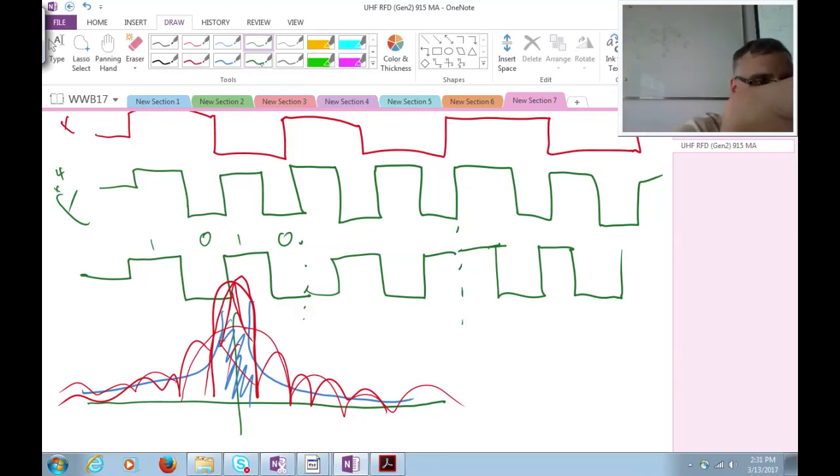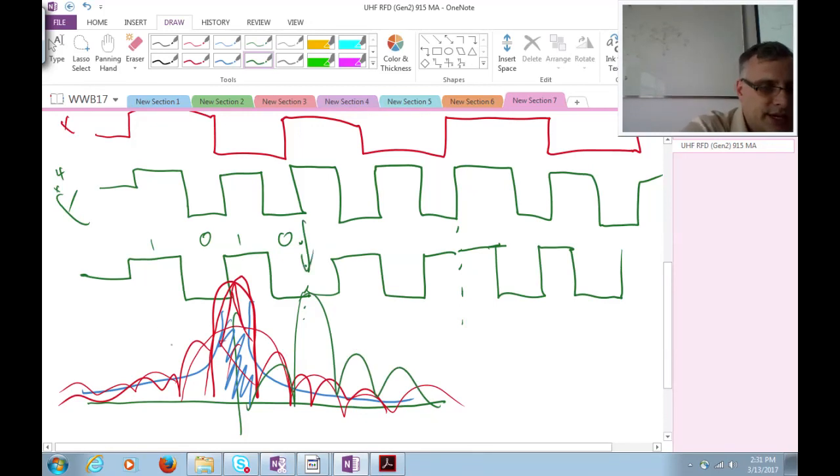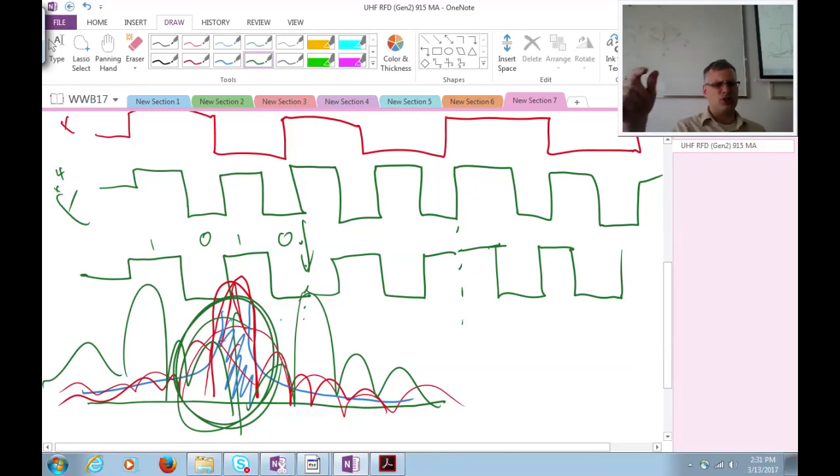So this green signal down here, for example, the spectrum of that signal will look kind of like this. There'll be a peak here and then a peak here, well away from my noise in my subcarrier. And the more transitions I add, the farther it gets away from the peak relative to the width of those spectral pulses. And that makes the signal to noise ratio go up. So this is the way to play that game where you slow down your transmission and get better signal fidelity, but you have to do this subcarrier modulation.